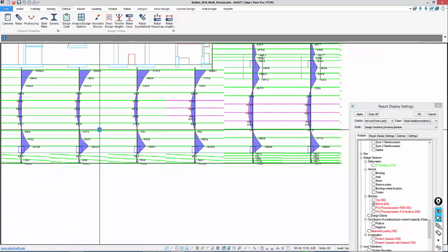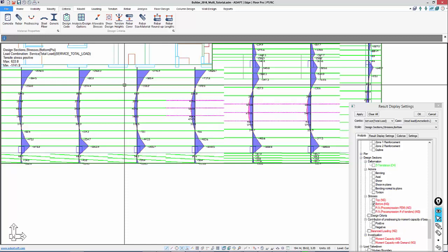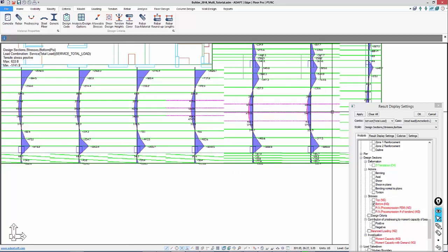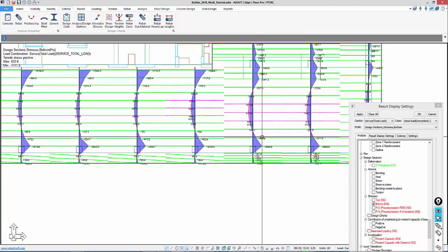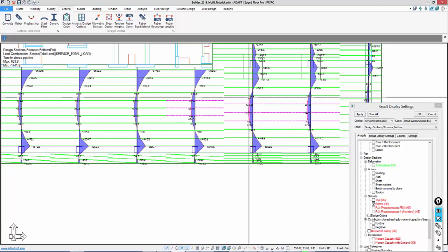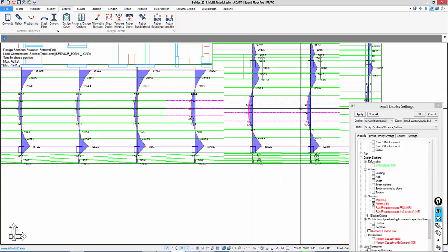So in this case, we already have maxed out drape. The only answer would be to either increase the thickness of the slab, increase the strength of the slab potentially, or we could adjust the number of strands. We might have to add more tendons to these banded lines. Naturally, we said earlier that we're going to increase the number of tendons for pre-compression. So that gives good cause to check pre-compression first and then go into checking stresses, because the outcome of having changed for pre-compression would have been something closer to normal or closer to the target for the stress check.